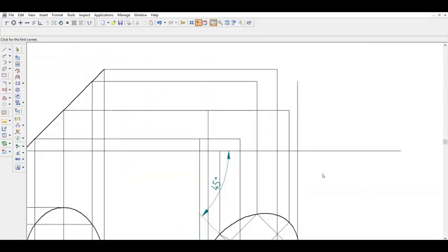Now after you have got 8 points, only understand this particular step. After you are projecting this, you have to go for an option called curve, just below the line. Select that curve. Before you go for curve, you just go for point, change the thickness to 2 mm. Now wherever you're having these points, you just place one point there, 4 5, and make sure you are placing it on end point. Okay, 5 6 7 and 8 points you are having it here. So just go for curve.